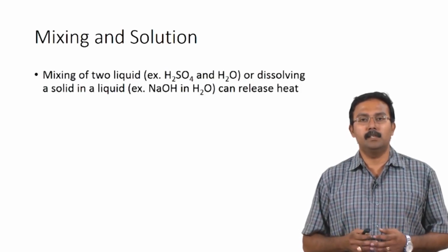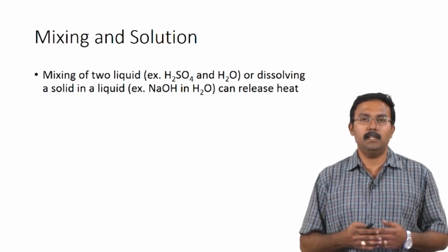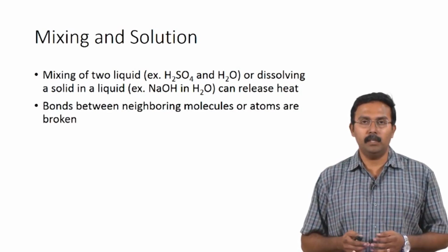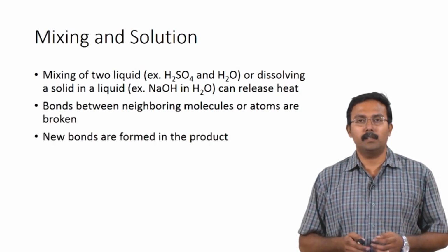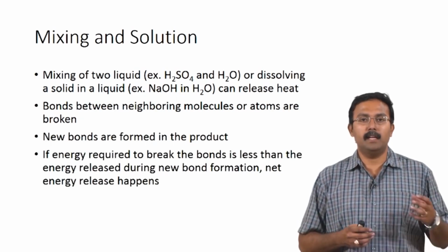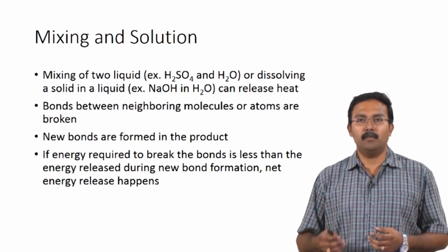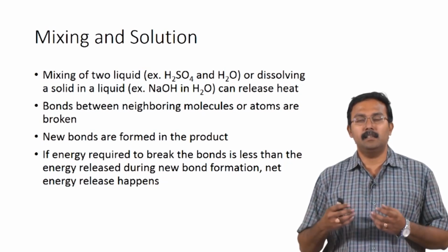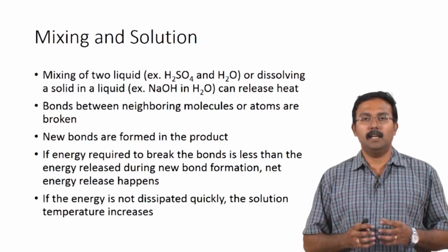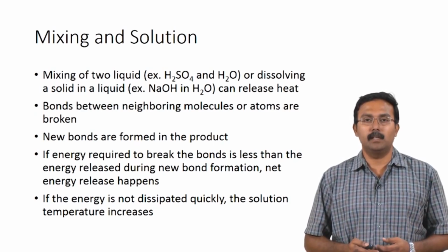Mixing of two liquids, for example sulfuric acid and water, or dissolving a solid in a liquid can actually release heat or absorb heat. Bonds between neighboring molecules or atoms are broken and new bonds are formed in the product. So, this means there is going to be energy associated with this process. If the energy required to break the bonds is less than the energy released during the bond formation, then a net energy release happens. If you have it the other way, then energy is absorbed. If this energy which is released is not dissipated quickly, then the solution temperature will also increase.